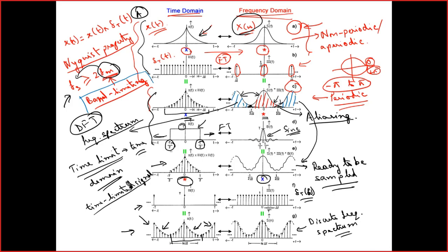The analysis of the DFT is a bit tricky, and it requires some expertise to analyze the discrete Fourier transform signal. Otherwise, you may be analyzing the extra time component as a periodic signal, and your analysis may be wrong.